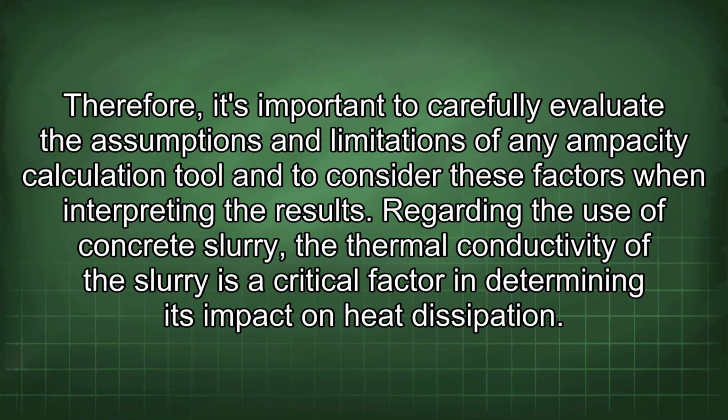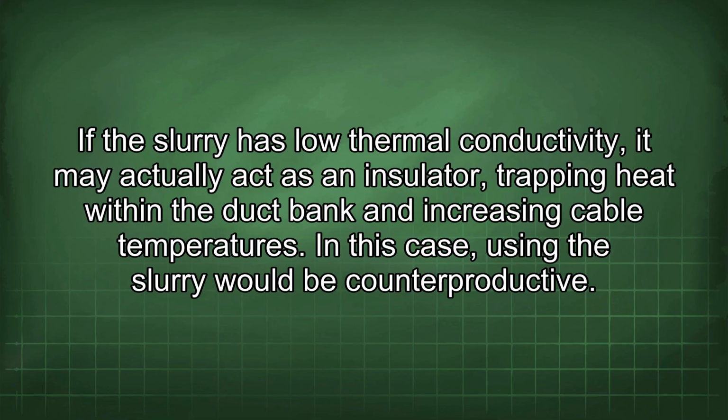Regarding the use of concrete slurry, the thermal conductivity of the slurry is a critical factor in determining its impact on heat dissipation. If the slurry has low thermal conductivity, it may actually act as an insulator, trapping heat within the duct bank and increasing cable temperatures.